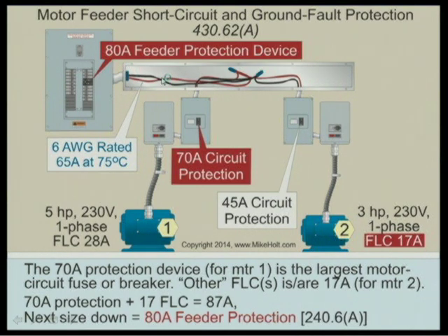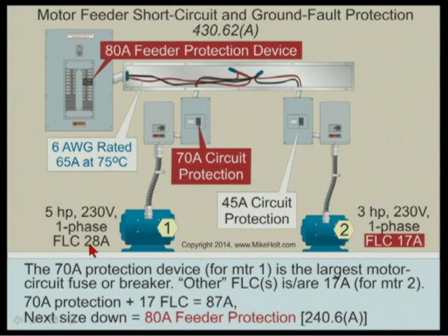Ryan, why don't you verbalize how you did that there? Okay, good point. I said it so fast. I take the feeder conductor rule in 430.24. I take the largest full load current, 28 amps, times 125%, which is 35. Then 35 plus 17 is 52, right? And so I need a 52 amp wire at 75 degrees C, Table 310.15(B)(16), and I guess that would be 6-gauge wire on an 80 amp breaker.